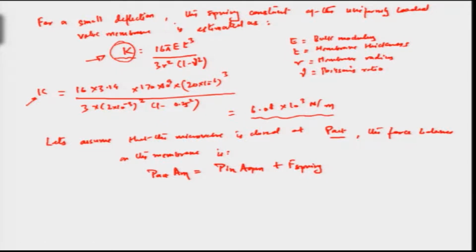So, let us calculate this force balance equation for two different conditions. One, when the valve is in an equilibrium state, and let us say we are talking about the equilibrium at valve closure, and we can also find out how this equation behaves at valve opening, as the actuation begins.